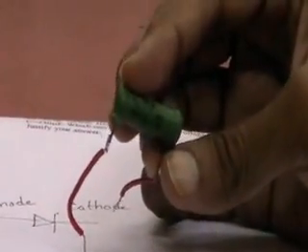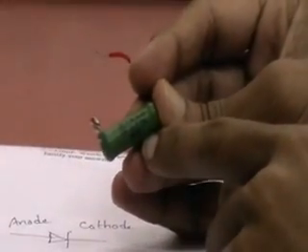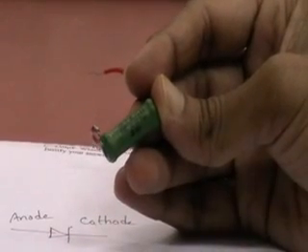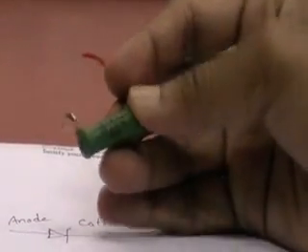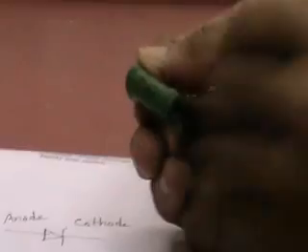This is not the ordinary carbon resistor. This is the wire wound resistor. Here the rating is indicated that this is a 1 ohm resistor. 1E means 1 ohm, plus or minus 5% is the tolerance. This indicates the power rating. Normal resistors with the same value cannot withstand high power circuits. So when current is high, we have to use this type of resistor as loads, so that we can prevent the resistor from getting damaged. This is a wire wound resistor, and this is also a wire wound resistor but of different value. 100E indicates 100 ohms.